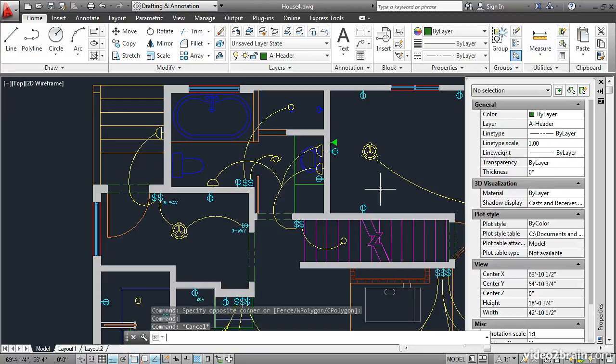You have learned how to load line types into AutoCAD using the line type command, how to change the global line type scale with LTSCALE, and how to override line type and line type scale on selected objects.